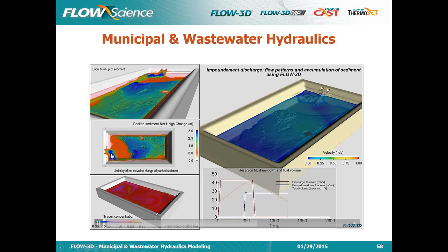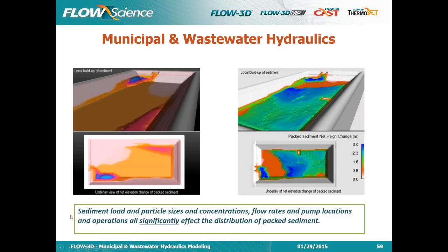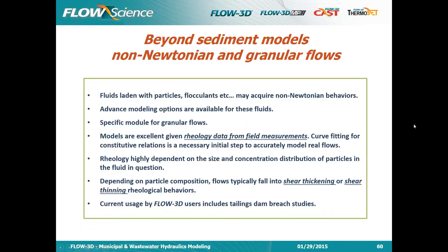And this is the top view of where the sediment has accumulated. This is a perspective view, and as the water comes down, you'll see where the sediment has accumulated, and then there's no more water to suck out, so we are left with these ponds. Yeah, that's pretty interesting. So sediment loads, particle sizes, concentrations, flow rates, pump locations and general operations all, of course, significantly affect the distribution of packed sediment. So you get some good insights from running these simulations.